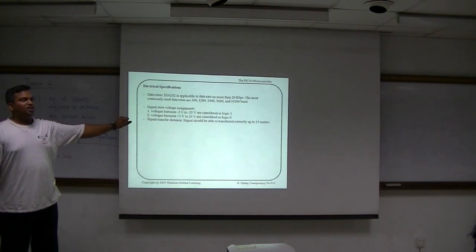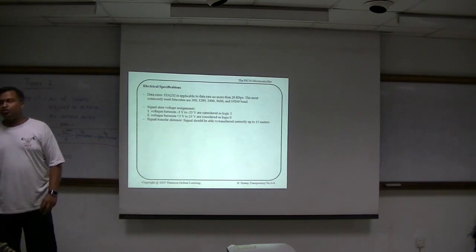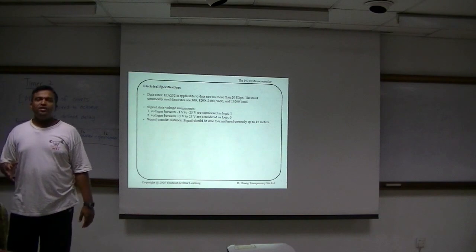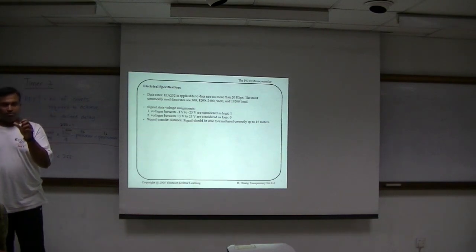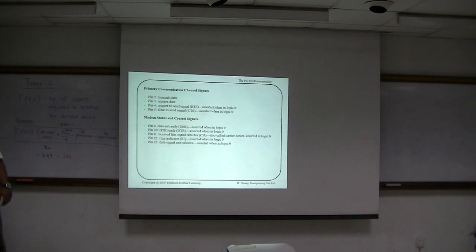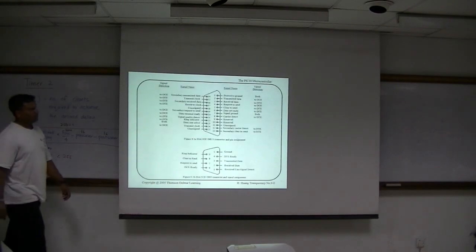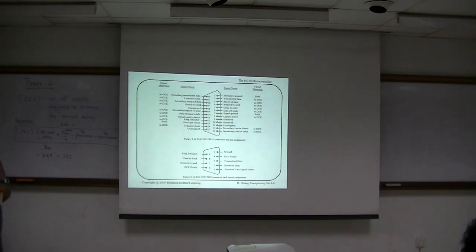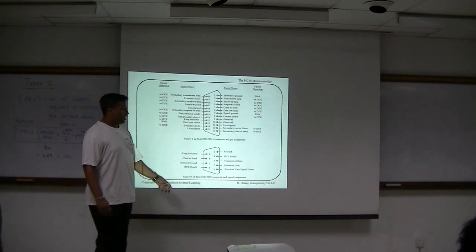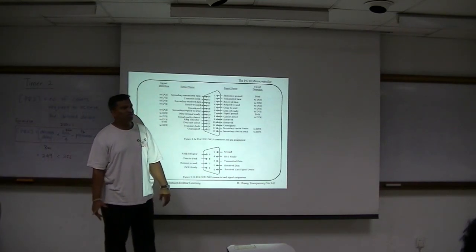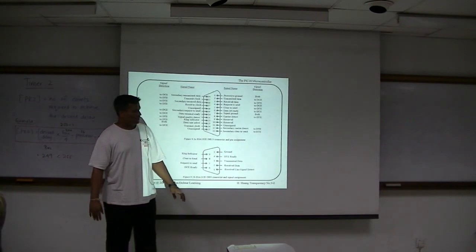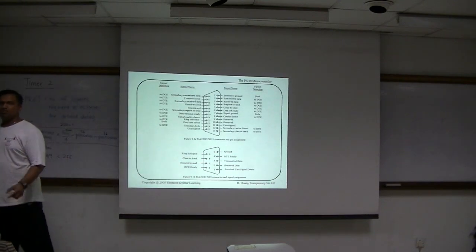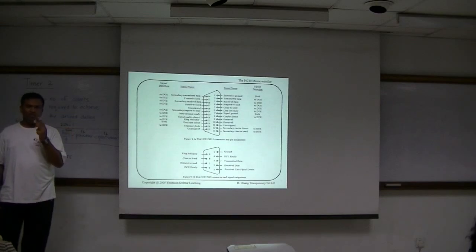This range is used only when you're communicating to a device which has an RS232 port, for example a computer. Your laptop doesn't have that, but old laptops have, or desktop PCs have, the serial port. Serial port looks like this. Out of all these pins, for simple communication you only use transmit, receive and also ground. Three wires is enough. Even though you see so many pins, if you cut the wire you would see only 3 wires connected.